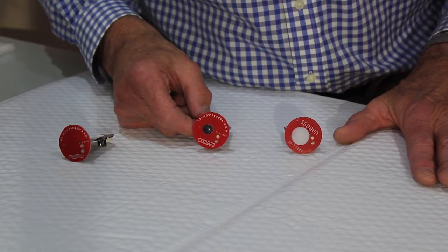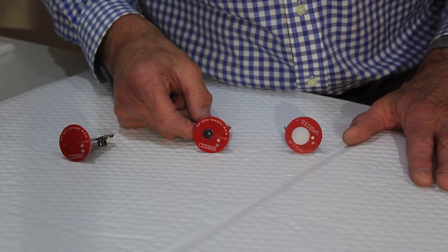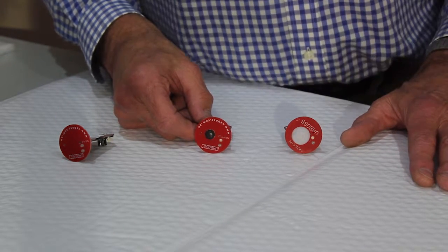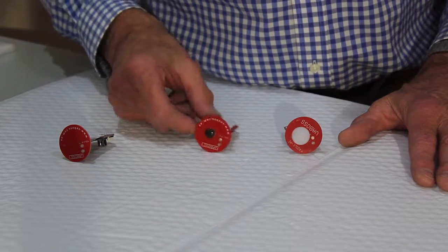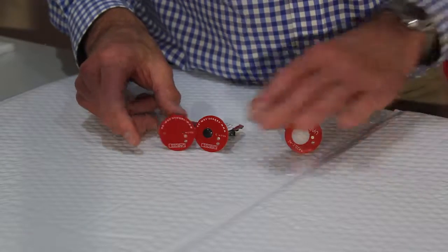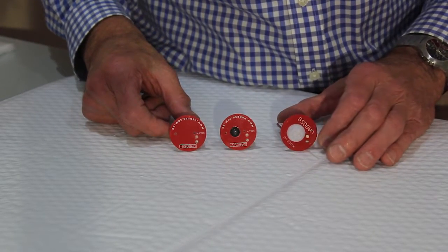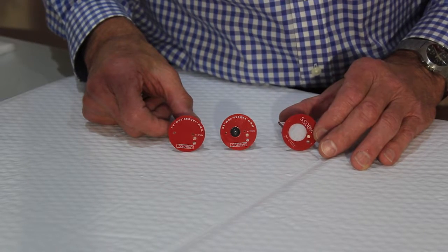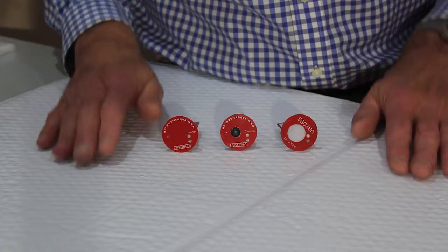maintain 80. If you have an area where you have some precision activity, such as scientific electrical work, you might want a lux level of as high as 400. This device will just maintain that, no matter how much light's coming through doorways, windows and skylights, it'll maintain 400. You won't even notice it. It just dims up and down ever so gently.